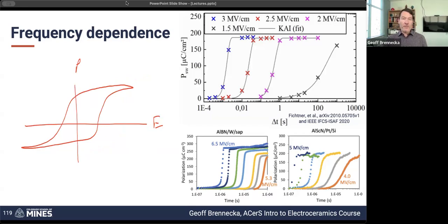Okay, so this is our baseline. If this material is leaky, now I'm going to go down in frequency this time. So if this is our baseline, kind of happy, perfect looking material, if this is a sample that conducts a little bit of charge when I apply field to it, as I reduce the measurement frequency, more of this polarization contribution is actually going to come from that conductivity.